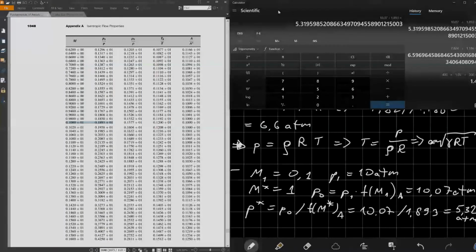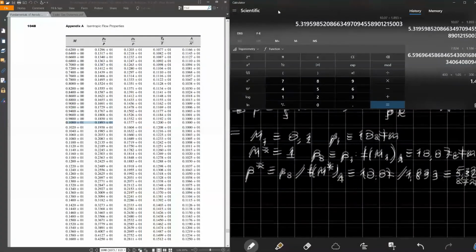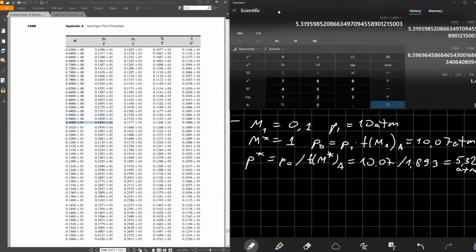That's the calculation. That's a simple calculation. If you would like to know other flow properties, for example, the speed of sound or the characteristic velocity, we need to also set some additional flow parameter or thermodynamic parameter inside the task. So not just Mach number and pressure, but also, for example, temperature or density, to calculate temperature and speed of sound.